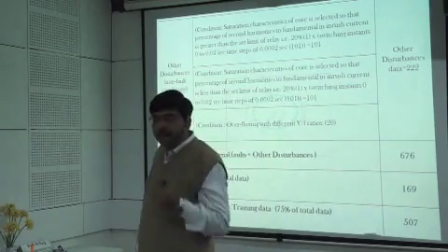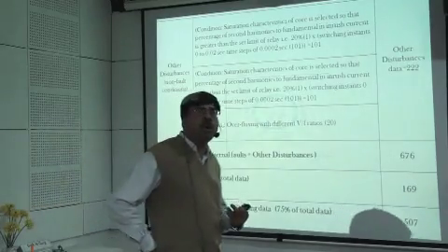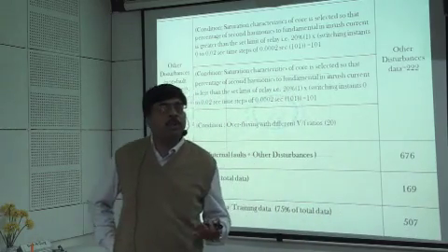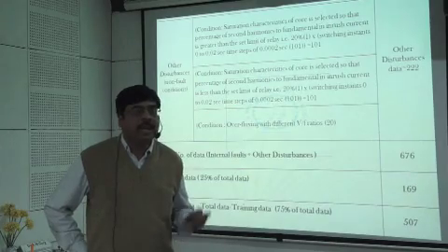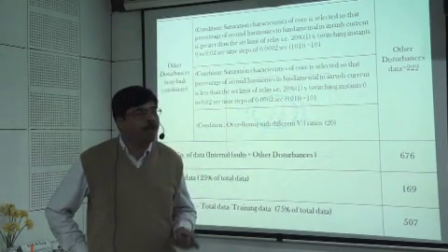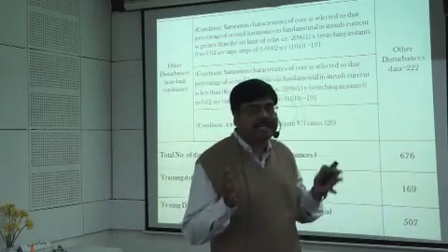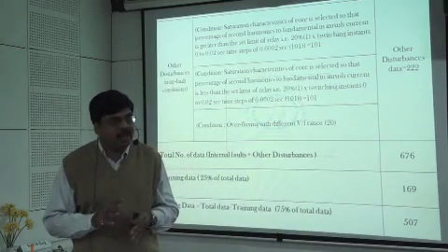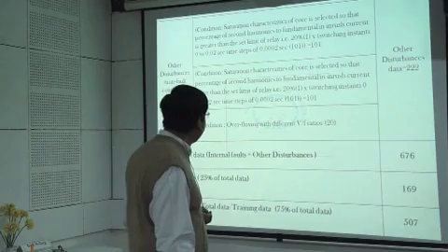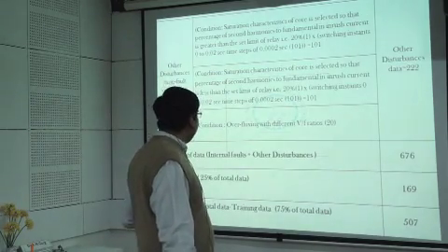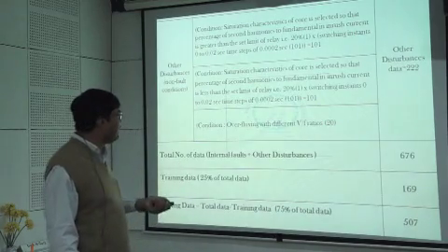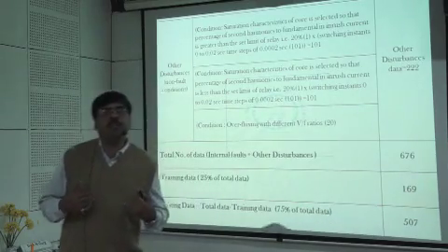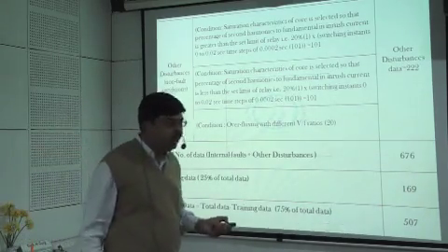Now the point is, in modern day power transformers, due to improvement in the core material with a view to reduce core losses, the amount of second harmonics is reported to be very less, even less than 7%. That's why differential relays based on harmonic restraint maloperate. I also want data of inrush so that the SHR is less. For that, in my simulation, I have adjusted the BH curve and thereby taken the data of inrush with various switching instants. I have also taken the overfluxing condition with different V by F ratios. Total data is 676, out of which I have used only 25% for training, and I will check the performance of the proposed algorithm for the new 75% eventualities.